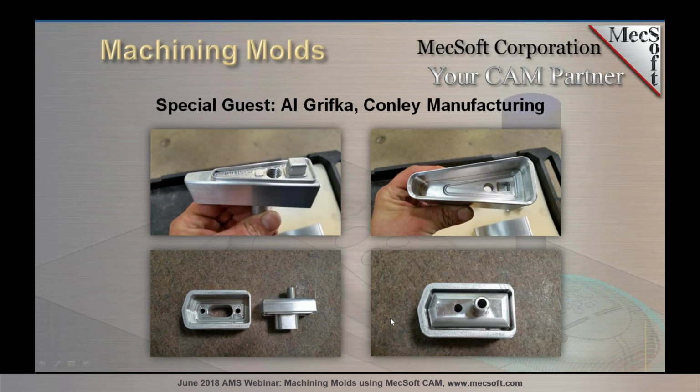This here will go right through that hole upside down, as you see, and there's key inserts in these holes here. A lot of times in aerospace, a lot of the material is aluminum, obviously to make it lighter, but they'll have steel key inserts on the insides here. So this part fits right inside here. As you can see in this picture, that's the parts mated together. On the end here, I believe it's a quarter pipe tap, and that's what they'll use to hook up their injection hoses and stuff like that.